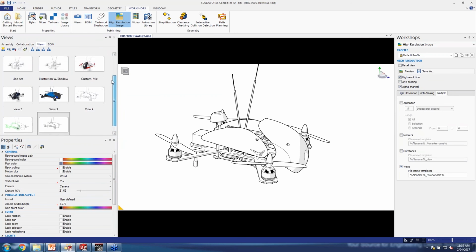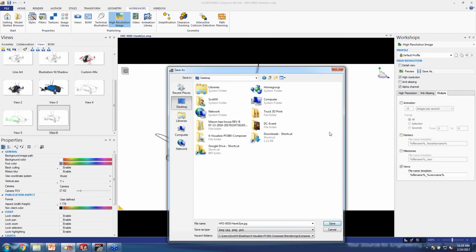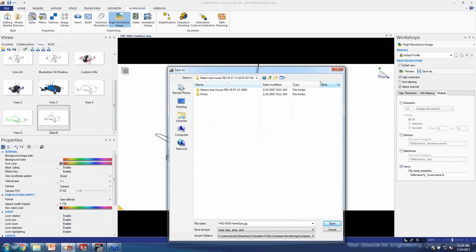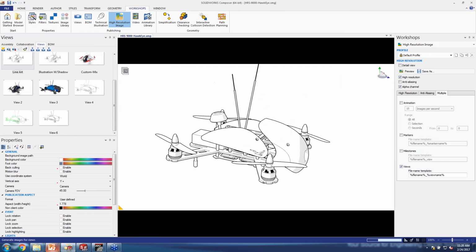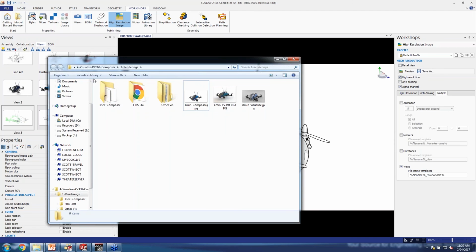Okay, so we've got 11 renderings. And what I'm going to do is specify my resolution. So, high resolution, maybe you want to go like 600 dpi on that. We're going to go ahead and say that the quality setting is all the way up. And I'm going to say all of the views, so all of these here in one shot. And so 11 renderings, save that out.